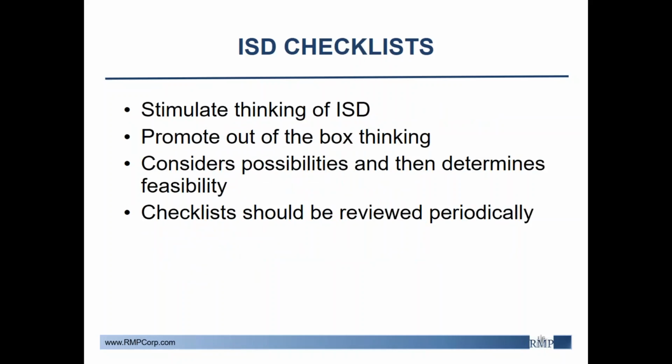So ISD checklists can be added at the end of HAZOP studies to stimulate thinking of inherent safety review for the overall plan, or they can be added within each node of a HAZOP study to stimulate thinking of inherent safety review for specific subsystems. Checklists are intended to promote out-of-the-box thinking for your team and to generate ideas that might be usable in an existing facility or a plant of the future.